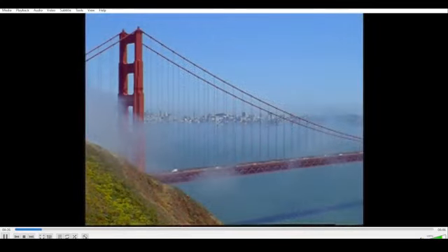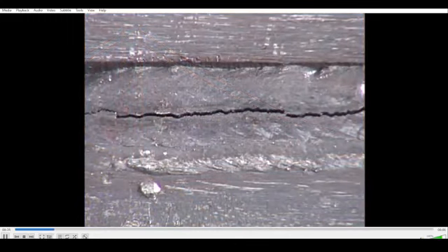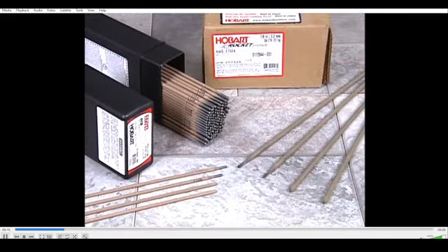The toughness of a material is extremely important when designing pressure vessels, bridges, ships, and other structures. The weldment must be able to resist the formation and growth of cracks within its operating temperatures. Through impact testing, base and filler metals are evaluated to determine their ability to provide toughness.